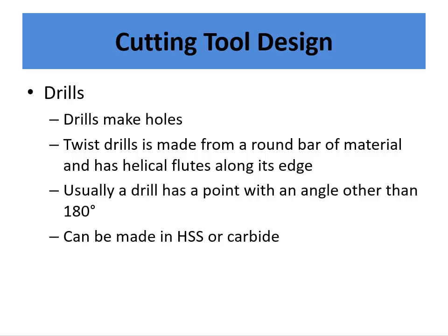Okay. And usually a drill has a point of something like 118 degrees, and usually other than 180 degrees, although nowadays there are some really good flat point drills that have good uses and work really, really well. And one thing that's important to remember about a drill compared to an end mill or something is drills only cut at the very tip of the drill. So what are called the lips of the drill. The lips of the drill cut, nothing else cuts. So the sides of the drill do not cut. There are certain drill mills and certain specialty tools that are kind of a combination of both. But a drill cuts at its point and along the lips, and that's it. It does not cut along the sides. So, you're not going to mill with a drill, okay?